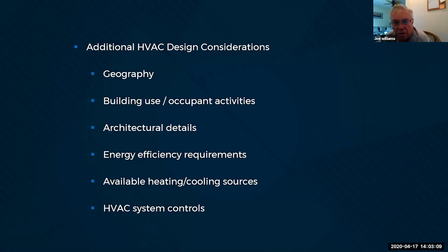Explain the difference, you know, if the water temperature is, say, 85 or 90, and you're still trying to reject temperatures on the inside, there's still a differential, and there's still a loss there. Explain that. Yeah, typically coming off of a chiller, your water temperature going back to a cooling tower or to a well is going to be in the neighborhood of 95 to 100 degrees, and we only need to bring that down about 10 or 12 degrees to keep the refrigeration cycle going.